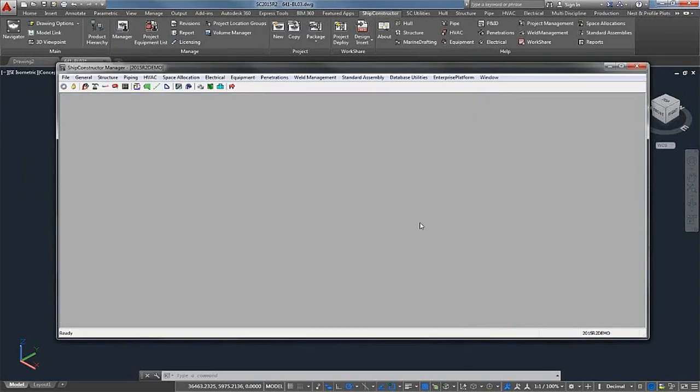What's also an advantage in this case is that if you have an equipment in your library that is actually having it be representative of a valve, for instance, even though that equipment part may not show up in a spool drawing, if you set its S key values when in its stock, then it will show up in the PCF file and thus in the isometric drawing.